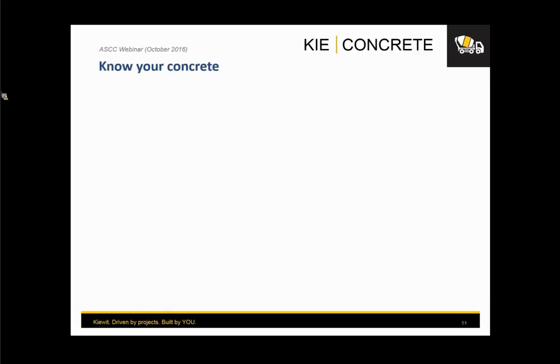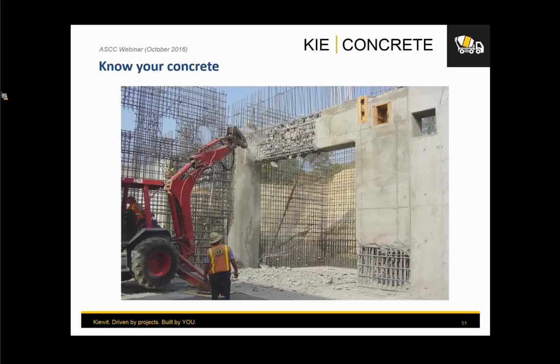What is the basic thing about a concrete placement? You need to know your concrete. You need to know what concrete mix is coming, right? What happens if you place the wrong mix? This is a key word project. What happens if you don't place the concrete mix that is supposed to be there? You have to take it out. You have to take it out. And it happens. It happens. I bet many of you have stories to share about that one.